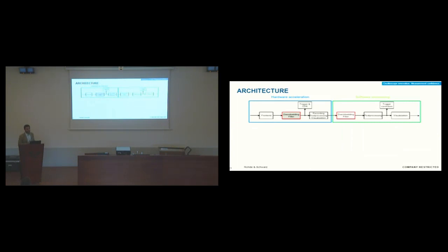So the de-embedding is not really new. You can find many solutions in the market that provide de-embedding, but they all do it in software. The signal is digitized and then loaded into the CPU, and with many calculations, it provides a de-embedding response, and we get the signal corrected. The problem here is that, first of all, it's a process that takes a really long time. So the oscilloscope will be very slow.